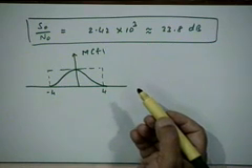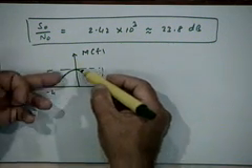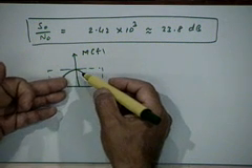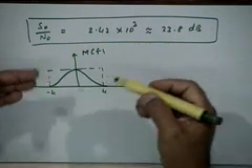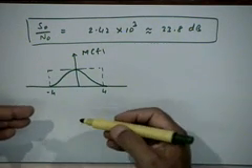a different transfer function which gives higher weightage to those frequency components where the signal to noise ratio is good, and lower weightage to those frequency components where the signal to noise ratio is poor. Not the pre-emphasis. This is as if the best filter to use at the final output would have to do with the kind of signal to noise ratio distribution you have across the bandwidth.